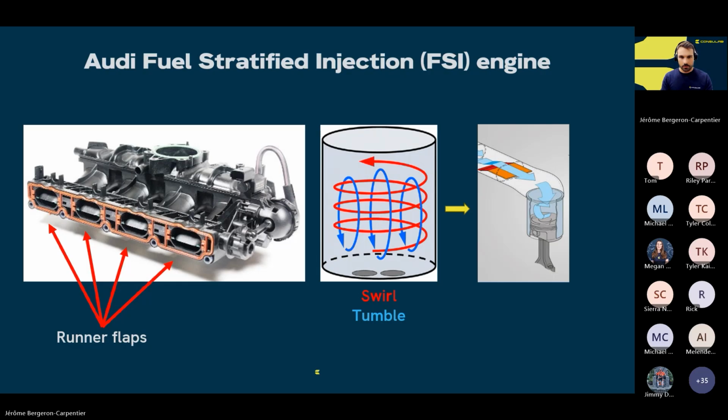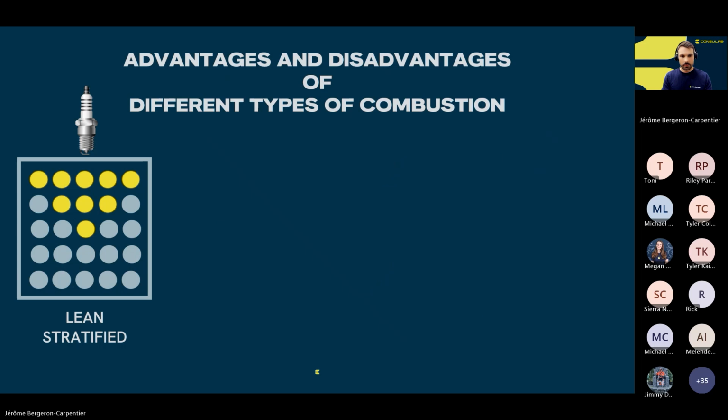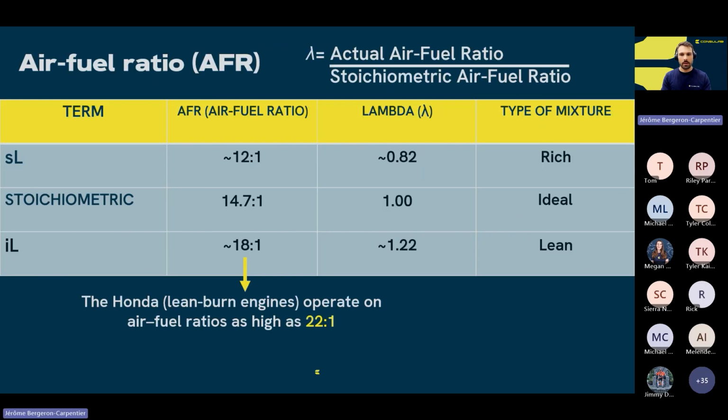So like I said, the whole strategy is about having lower fuel consumption, but we don't want to be only running lean, because that's going to create some problems with our engine, and probably some problems with the pollution that our engine generates, which can't necessarily be treated by our catalytic converter.